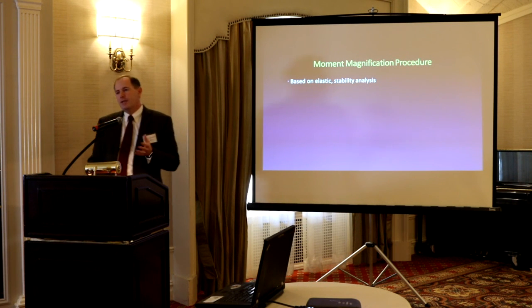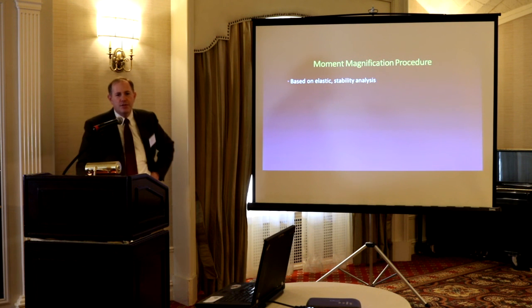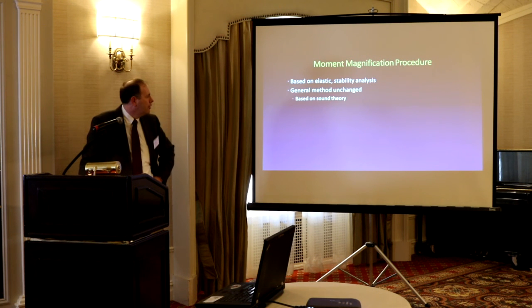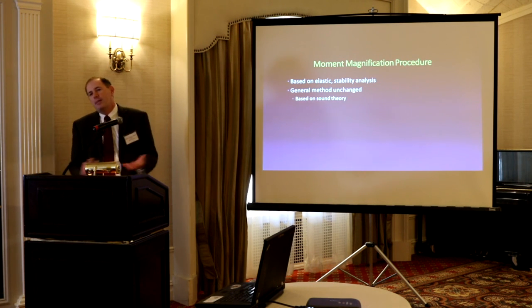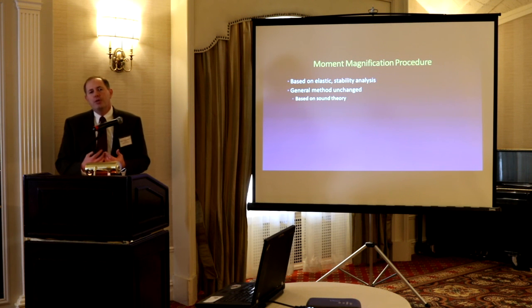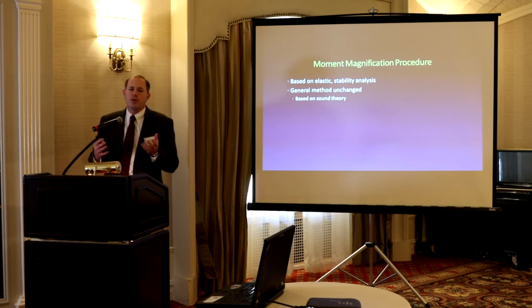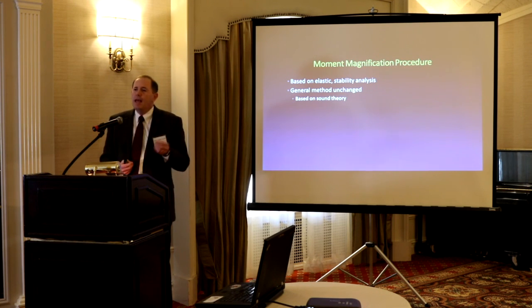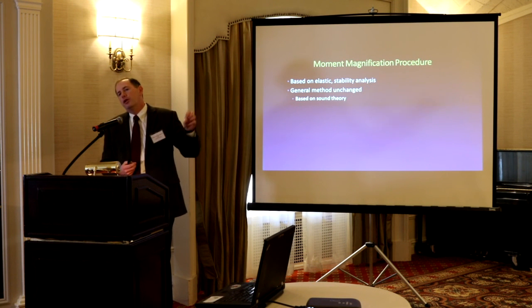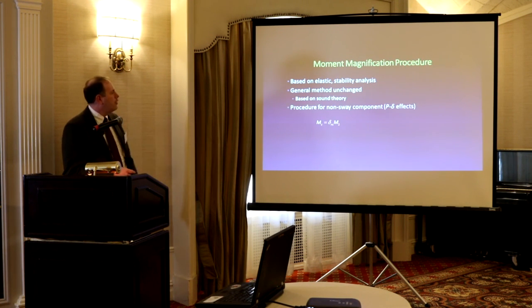It's based on elastic stability analysis. Timoshenko, if you go back and look at some of that, this is very classical work. The general method that we're going to talk about, which in the code today has remained unchanged, turns out to be a great method. I mean, that's how it works. There's a simple equation looking at small deflection theory. It doesn't mean that they're that small, but it assumes small deflections and a shape, a sine wave, for the deflected shape, and unless you're right near the buckling load, the answers are very good. So it's a sound theory.